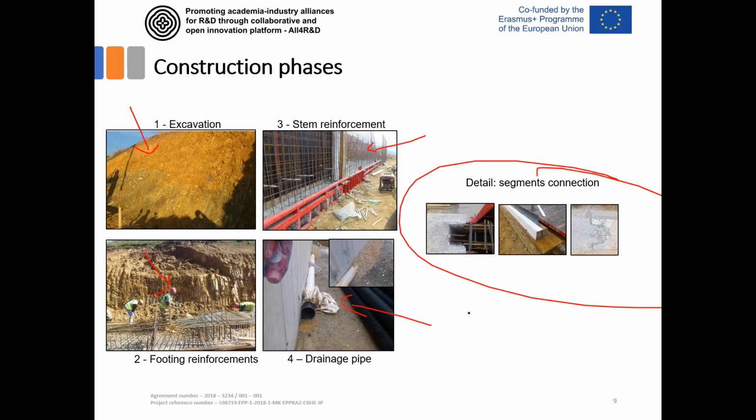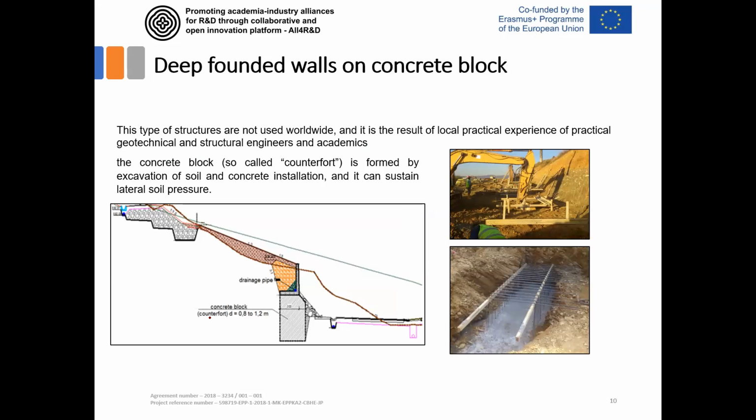If you build the wall in segments, and you usually do, since it's not very good to excavate all the wall at once, since some local failure could occur from the uphill. So it's better to prepare this excavation in segments.